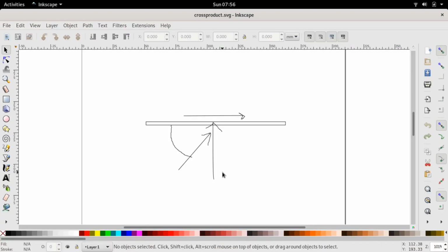Now the concept is, in this case, Fleming's left-hand rule assumes that they are all 90 degrees to each other. But they need not be at 90 degrees to each other. It is quite possible that the field and the current are not at an angle of 90 degrees but at some other angle. So for example, coming back to our diagram, let us suppose that this is the magnetic field, right?